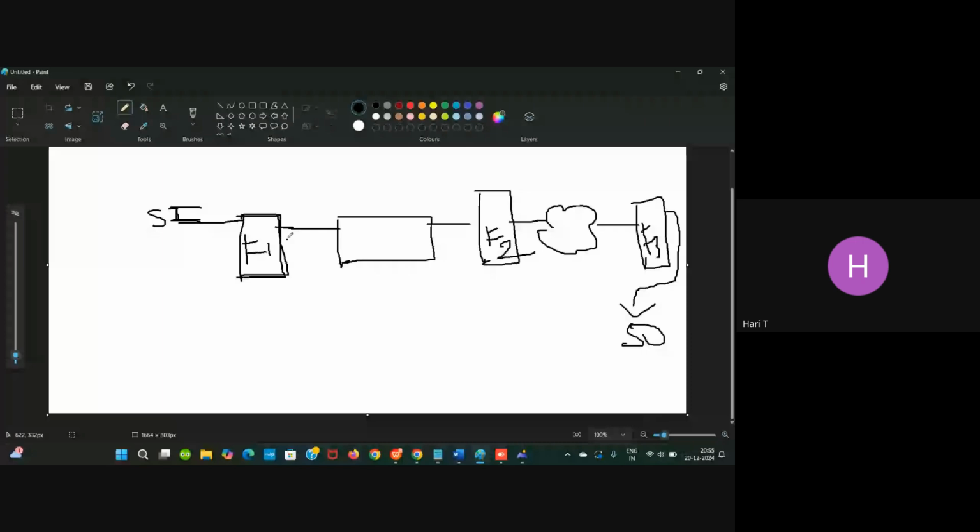Whether the chain is connected properly or not, we can perform the chain test, the scan chain test, as we call it in DFT. It will make sure that every scan flop is interconnected and stitched properly. In order to test this scan chain, we will enable the scan enable. It will be high.